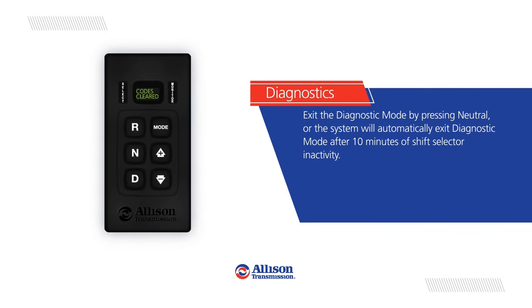Exit the diagnostic mode by pressing neutral, or the system will automatically exit diagnostic mode after 10 minutes of shift selector inactivity.